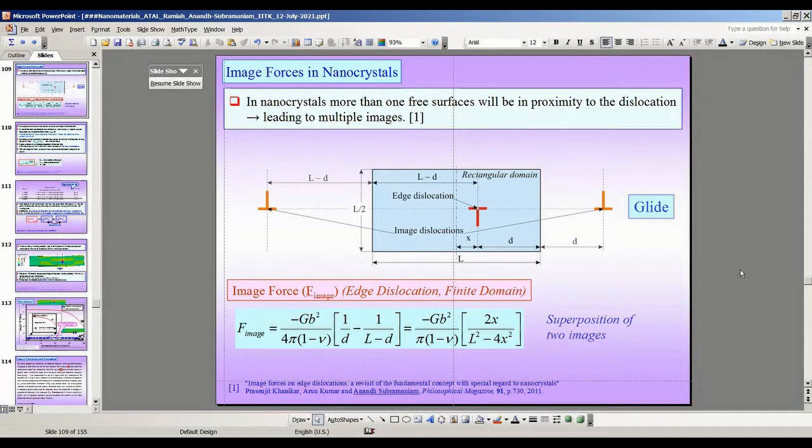And the stress you require to drive a dislocation is called the Peierls-Nabarro stress, which is the shear stress at the slip plane level. Now you keep on reducing the size of the material. A normal material has a lot of dislocations in it, and these dislocations help you in doing plastic deformation, what is called plastic deformation by slip. But when you go to smaller and smaller sizes, these dislocations are attracted to the free surface by an effect called the image force.